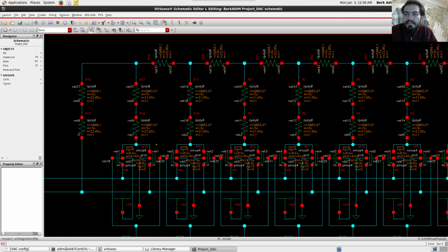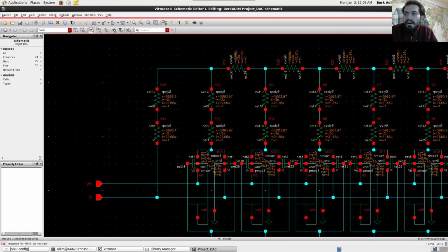We are not using full transmission gates because for the high switching portions, we know the source will always be connected to high, so we can comfortably use PMOS, and for the low switching portions, we know the source will always be at the lowest voltage, so we can comfortably use only NMOSes.